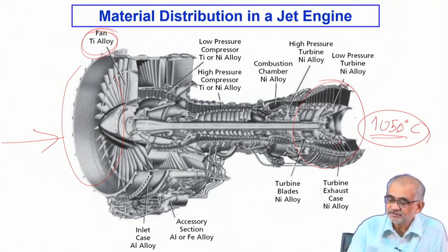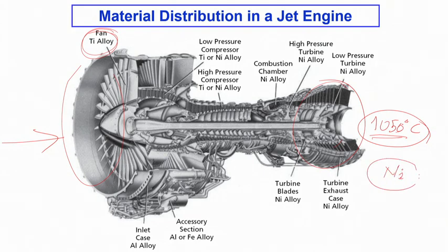Now when you want to prevent oxidation of nickel based superalloy, you have to realize that if the body is made of some nickel based alloy, then on top of that ideally you would like to have coatings of, let's say, zirconia. Now zirconia, obviously if it can bond well with nickel, there is no problem, then it can prevent counter ionic transport.